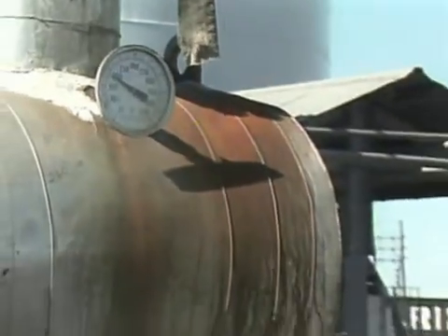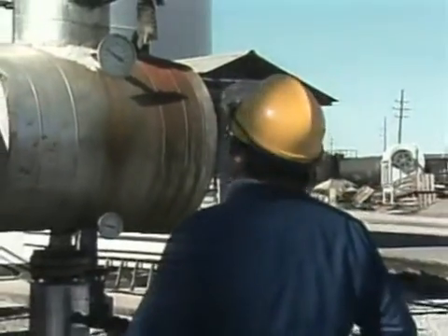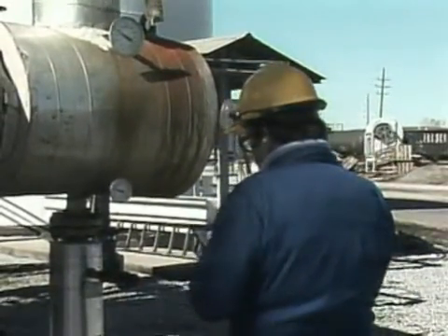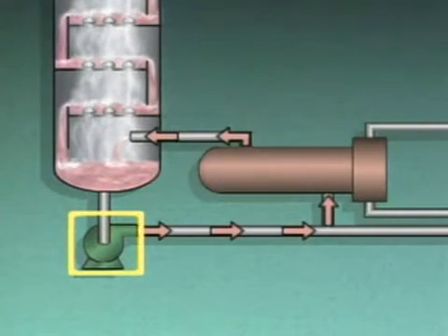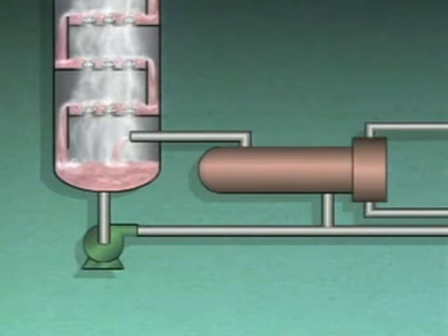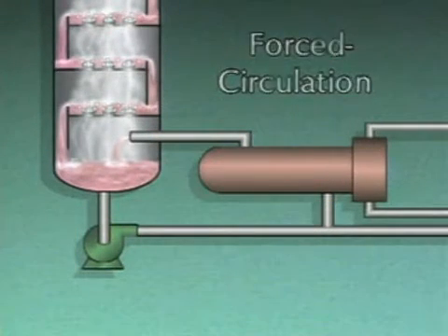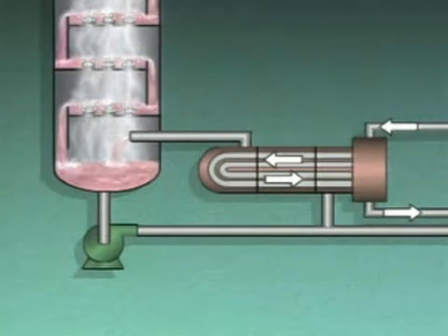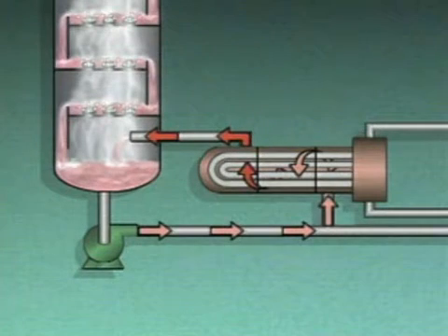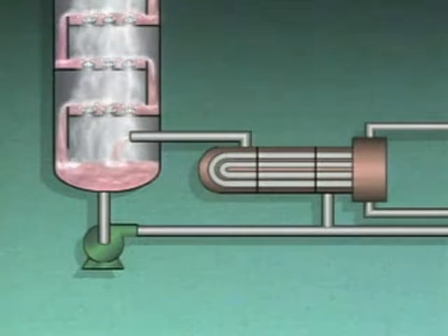If the reboiler in a distillation system isn't operated correctly, problems can occur and the distillation process can suffer. For example, the shell and tube reboiler represented here must be started up a certain way to prevent damage and product contamination. A pump is used to circulate bottoms mixture through the reboiler, so this is a forced circulation system. The heating medium for the reboiler is steam. The steam flows through the tube side of the reboiler and transfers heat to the mixture flowing through the shell side of the reboiler. During the startup of this reboiler, before any steam is supplied, the reboiler must be full